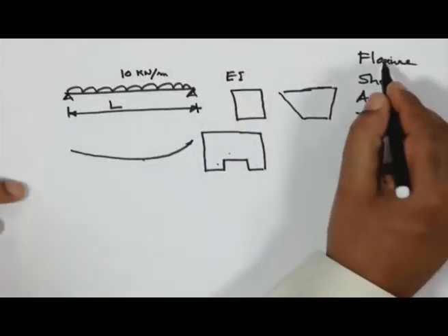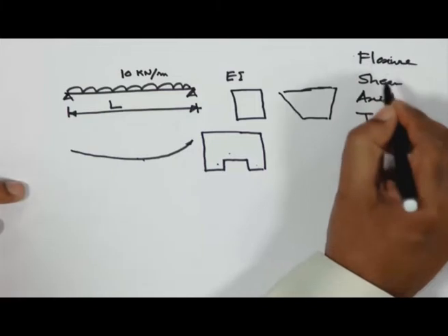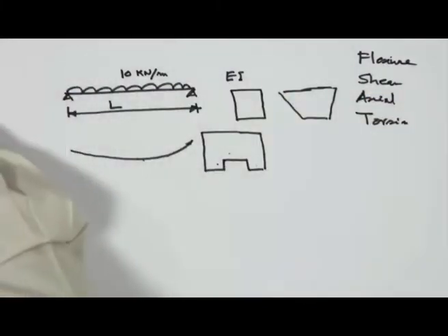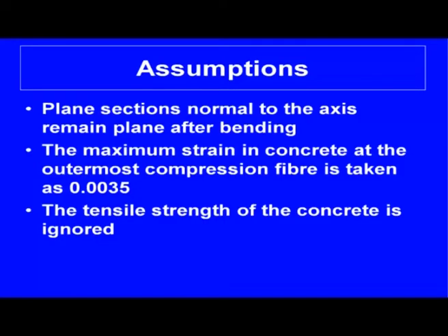Reinforcement will arrest this. That way you can consider that one, but the stirrups are very important here. By combined action of concrete, meaning concrete itself will take, and shear steel. So the concrete contribution is due to the transverse shear carried by aggregate interlock and dowel action. So these are what is there. That means the beam will take that. Now just to inform you, students, you are asked one question, for the column.